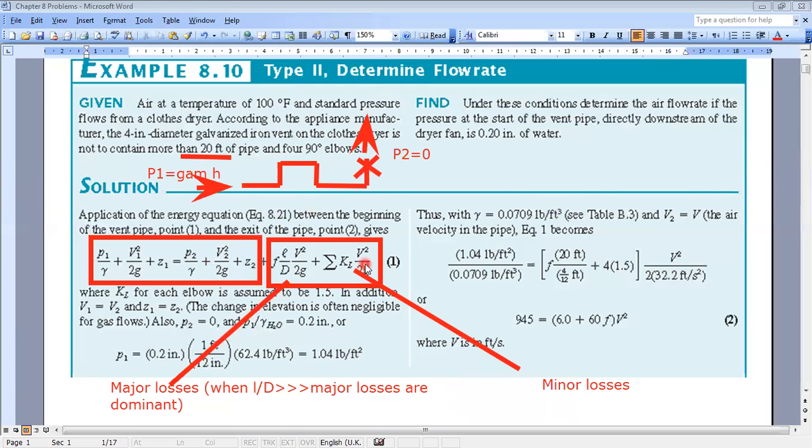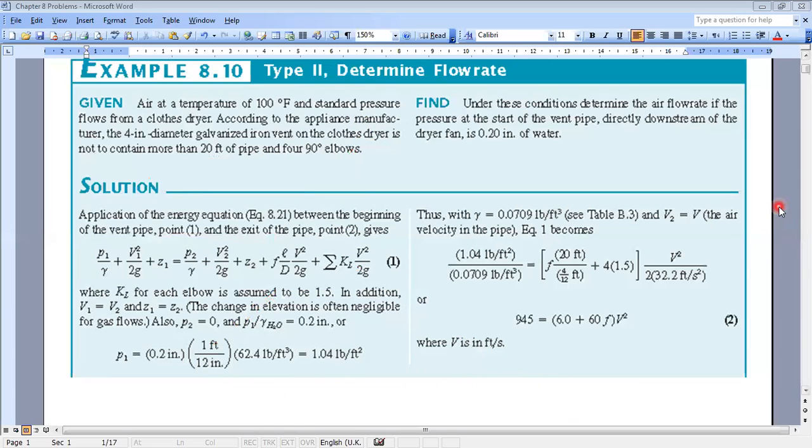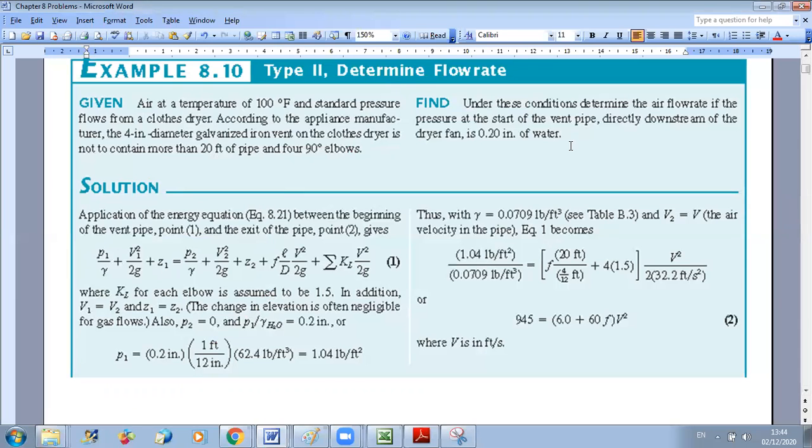Now, in order to know what is the loss coefficient for an elbow of 90 degrees, I should go to tables. So in general, they give me tables, they give me figures to find my loss coefficient. So I will go to the table which will give you the value of KL. In general, in the exam, we give you figures, and you will see that some figures will be repeated during the examples, and all are present in the book.